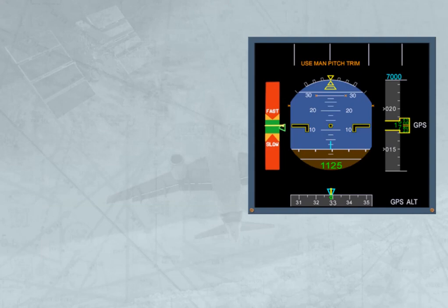The scale is divided into 5 colored ranges. A red upper area above Vmax with decreased load margin. An amber and red upper area between Vmax with decreased load margin and Vmax with normal load margin. The green area is in accordance with the normal speed range between VLS and Vmax. An amber and red lower area between VLS and Vstall warning. And a red lower area which indicates the stall speed area.